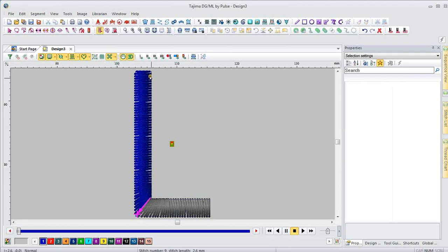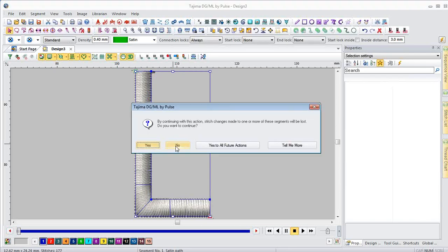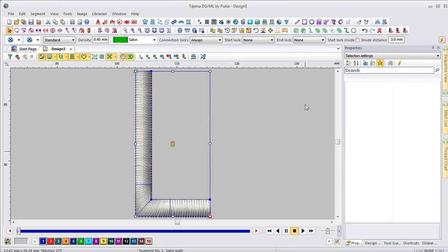A professional digitizer, because he knows what's going on, would basically pull the stitch a little bit more to the left and the right in order to gain this difference and the bigger tension in the beginning of the corners. Obviously, I cannot go into every segment I'm doing and do this. I can take advantage, though, of version 14.